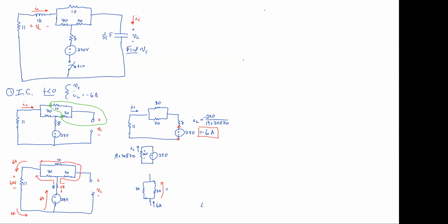What's the equation? One shot, one kill. So I'm looking for the equation for the current flowing through this 30 ohm resistor. Because once we find it, we've now found the current going through this right branch. And once we find that, we know the voltage across the 20. And once we find that, we find VC. And we've done it all without doing any matrix equations.